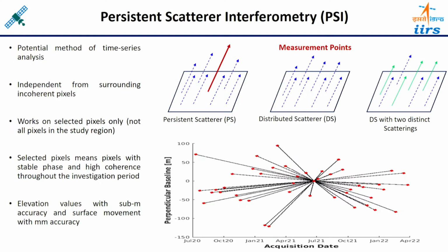So that is only possible if you are taking the reference almost in the middle, but you cannot simply choose the middle; you have to do the calculation according to the relationship which I have shown in the first slide. If you do that analysis using that relationship, then automatically you will get the reference image almost in the middle. This way we form the interferogram and generate the time series of the phases between the reference and the secondary images, and those phases are converted into deformations. So the time series of the deformation can be achieved.